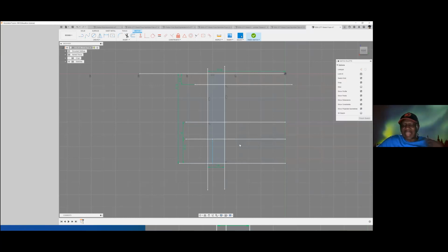You can draw the line and apply a dimension. Once you apply the dimensioning, it will show you the dimensions, and all these are very easy to do. The next thing I'm going to do is turn all this into construction lines. To turn one of them into a construction line, all you need to do is mark it and press X. If you mark it and press X, you can see that I have made this a construction line. That pressing of X is a toggle. Let us say I have a construction line marked. If I mark a construction line and press X, it turns it into a regular line. So I can use X to toggle between being a construction line and not being a construction line.